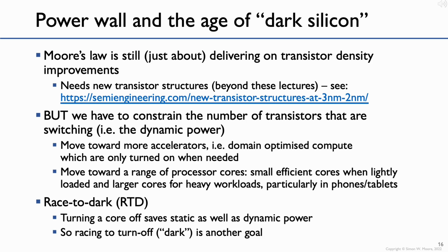That's a dedicated piece of silicon that's been optimized just to do video decompression, and therefore it's very power efficient. We turn that on only when we need to do video decompression, and then typically some of the processor cores and other bits of the chip will be put to sleep or into a lower power mode to allow that video decompressor to run. And that does result in enormous power savings.